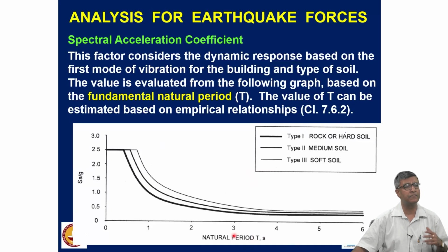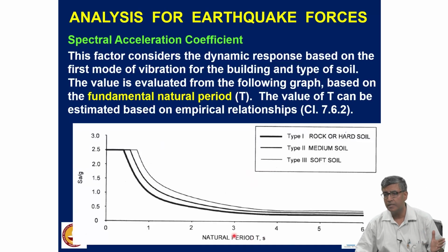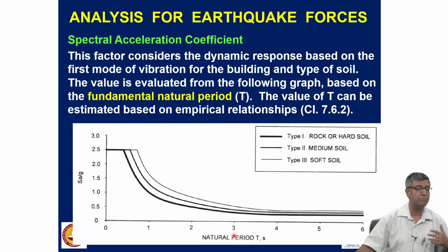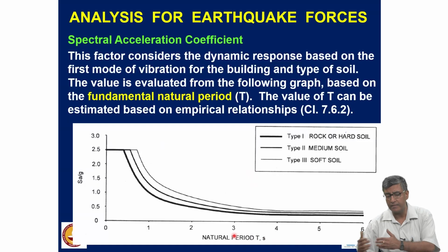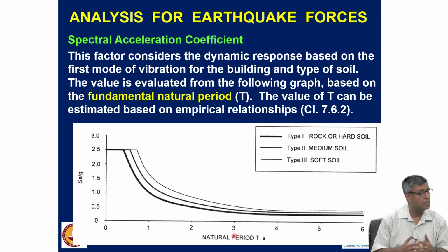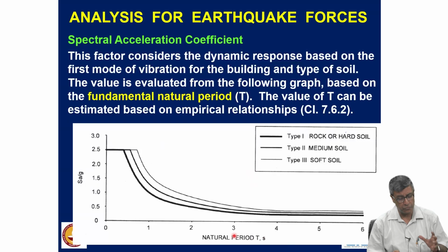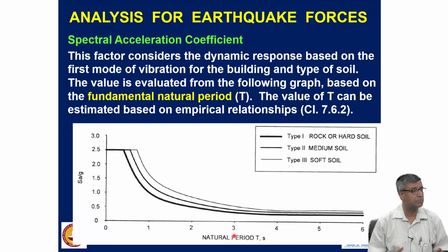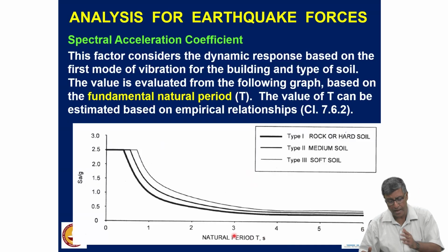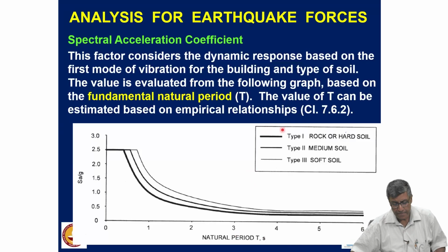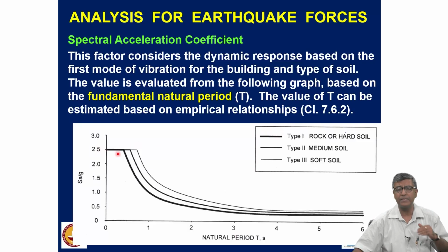Please note, in physics, we talk about a function of the frequency. Even for machine vibrations, we talk about functions of frequency because it is convenient to handle them. Whereas for buildings, the time period is more convenient to handle, and hence the response spectrum. These curves are called the response spectrum. Why spectrum? Because it is a curve with respect to the different frequencies or time periods.